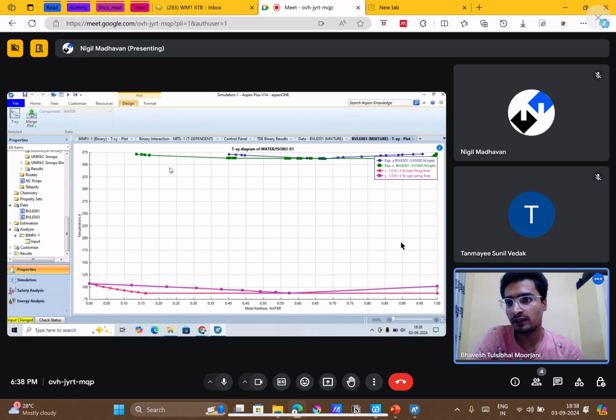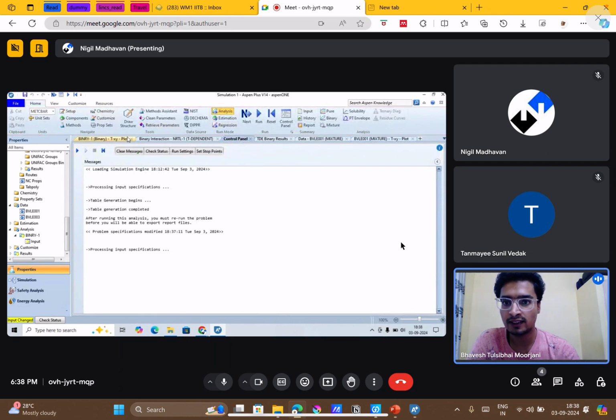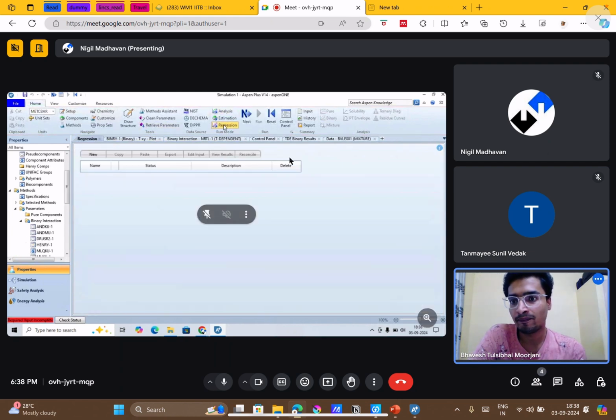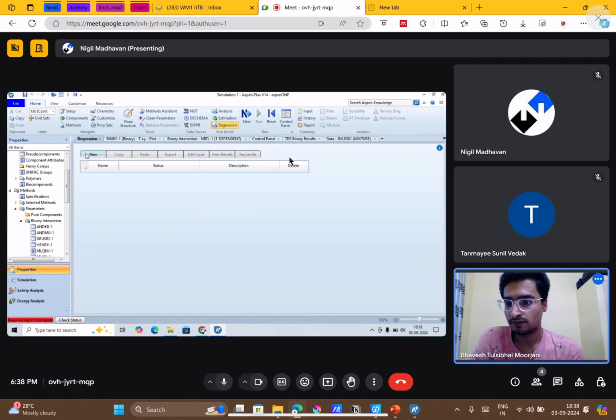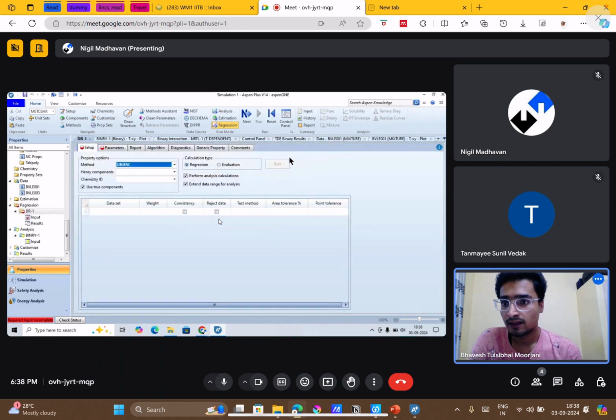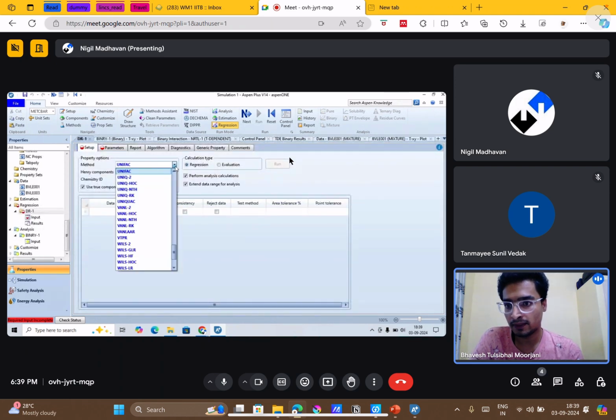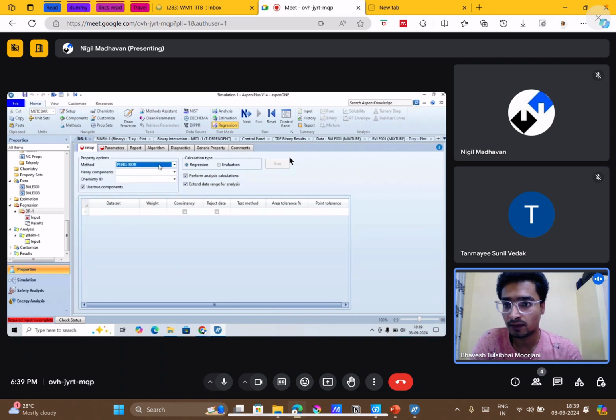So for that we have to go to the regression part. So can you go to the home? Yeah, in the regression on the top toolbar. Yeah, select it, click new, DR1. Yeah. So first we want to modify the Peng-Robinson method, so select that. Okay, yeah, Peng-Robinson, and the data set. You can click the option, and we want the 001 data set, right? So first data set, yeah, select that.